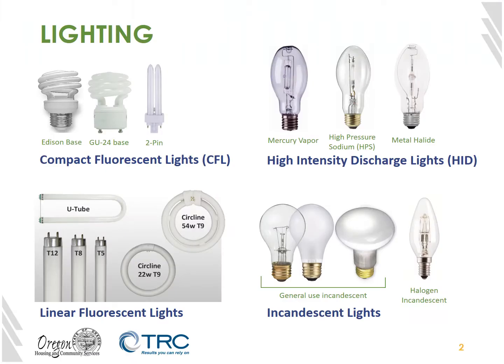The first type of system that we'll be looking at is lighting. Lighting comes in several levels of efficiency. Incandescent lights are the traditional bulb type and are the least efficient, with much of their energy being turned into heat rather than light. HID, or high-intensity discharge lights, are somewhat more efficient and are typically only used in high-power situations such as floodlights. Fluorescent lights have a large variety of form factors as seen here and may be compact or standard size. These were the most efficient form of lighting until the advent of LEDs.